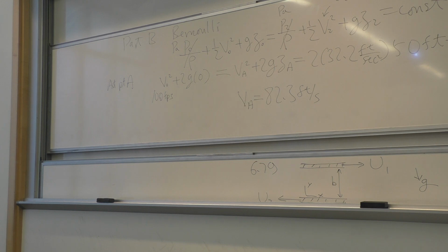Question on that? Yes? You could get the same answer because the x velocity doesn't change, and you have a way of finding the z velocity. So you could just do the triangle. Absolutely. You can get the velocity at A from purely particle dynamics on the right side of the board. This is just to tie in the whole big picture of Bernoulli, how it can apply to a water jet, and specifically in preparation for a potential PE exam problem. That's quite common, and it's a very doable problem as you apply Bernoulli, just like we did, but you get the same answer.